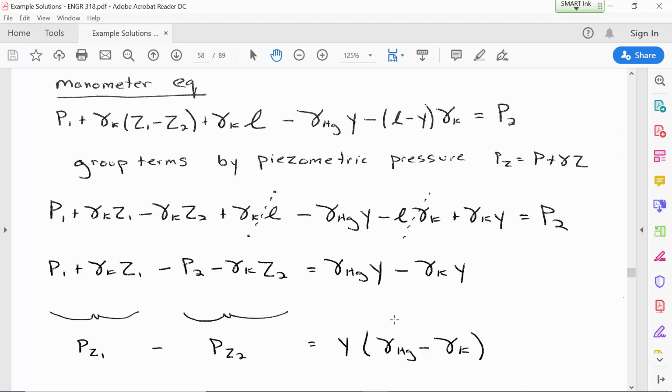What you remember about a differential manometer is that if the flow velocity is 0, then the two sides are going to be equal. That deflection only sets up when there's fluid moving through the pipe because there's a change in pressure. And so what the differential manometer in this case is measuring is the energy loss due to pipe friction. So even if we incline the pipe, there would still be no deflection if the fluid isn't moving.